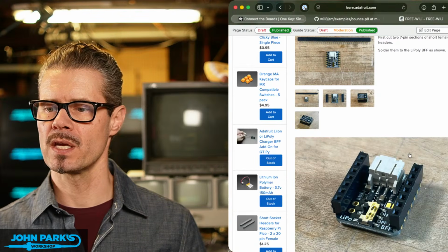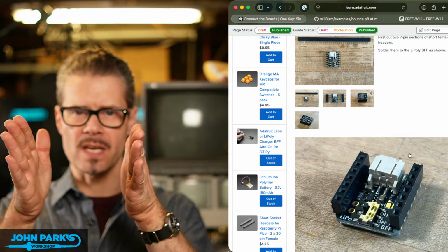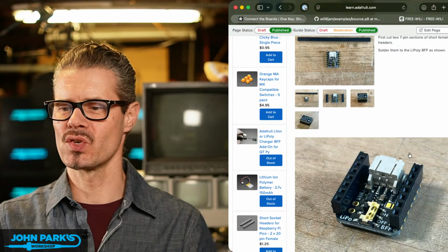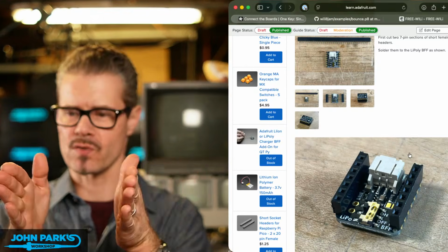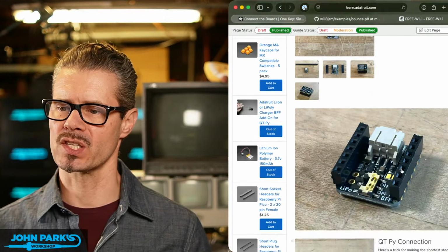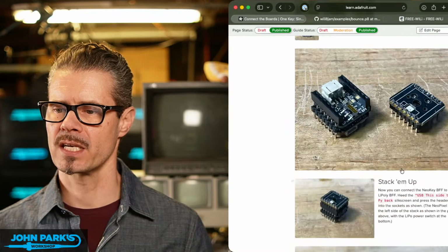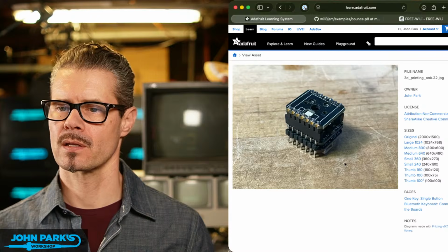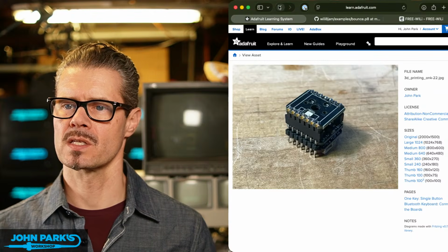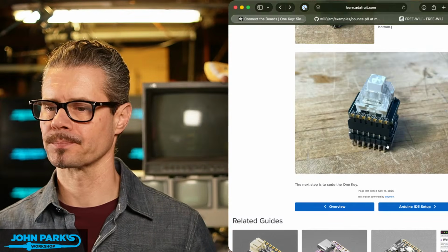And then we are going to create an outside of the pads connection using the little castellated pads. So they have connectors for sort of surface mount, but we can abuse that a bit and connect to the sides of them. So that gives us this nice little stack here. See that there? That's the nice little stack that's inside. And you can still pull them apart.